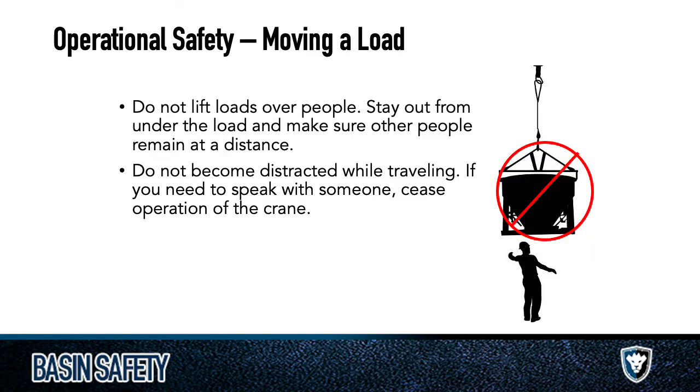We call these suspended loads once the lift is engaged. So once you have tension on the lift line, we have a suspended load at that point. No part of a person should be underneath a load. Not a finger, not a foot, not a head, not an arm, nothing. If you have a tag line, you want to keep that thing taut, and you want to maintain as much safe distance from that load as is physically possible.